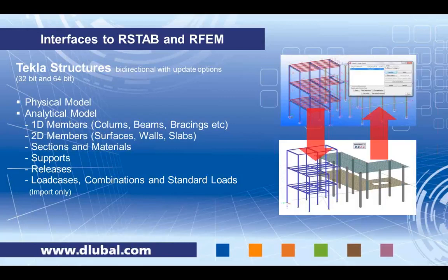When we exchange data from one system to the other, we have to deal with conversion of different section names and material names. What we might use in the bill of material in the BIM software or in the CAD software might not be the correct code designation of a material or cross-section in the analytical model.